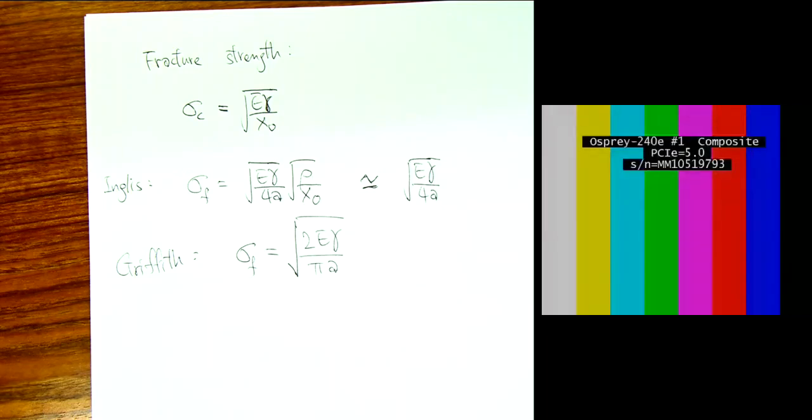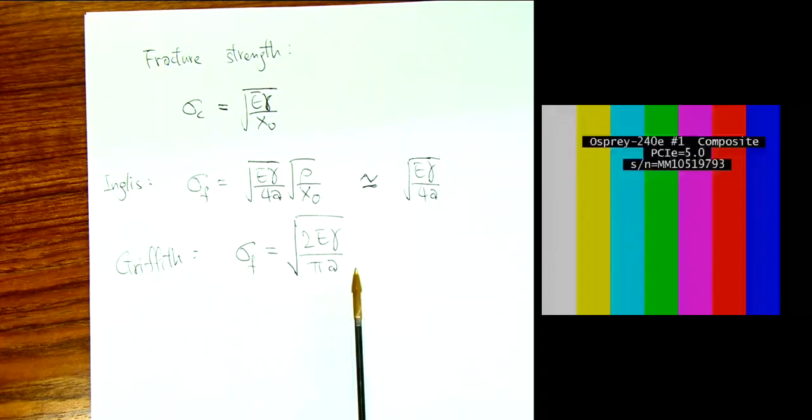So let's take a look at these. Let's compare these two. In principle there are some similarities and differences here, right? What is the similarity? Well, they both have the crack length a in there. So that's the flaw size dependence that appears in both of them, obviously because they both recognize it must be there. What is important is that they both predict sigma varies with 1 over square root of a. They both have that relation, and then you multiply by some constant, right?